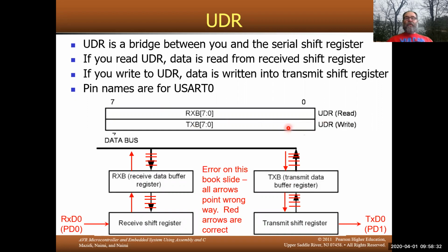Now, so far, 3 times 62.5 nanoseconds have elapsed, maybe as much as, say, 6 times 62.5 nanoseconds have elapsed. I'm still in the process of transmitting the first start bit of the first character out of the transmit shift register. So the T is sitting in this data buffer. The S is sitting in this shift register being shifted out. First start bit is in the process of being shifted out.